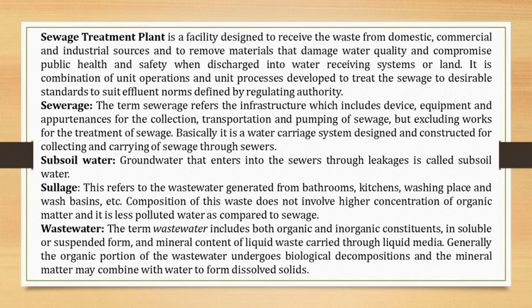It also uses similar unit operations and unit processes to treat that industrial waste. That means the removal of BOD, color, COD, alkalinity, and volatile solids. All of these are carried out at the ETP, effluent treatment plant, and finally this waste is disposed into the receiving system, that is a water body or over the land. So that is called ETP, effluent treatment plant.